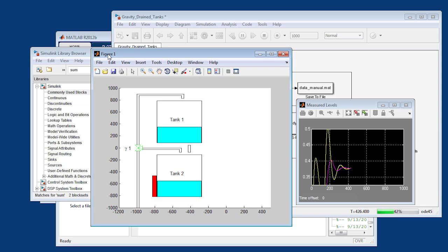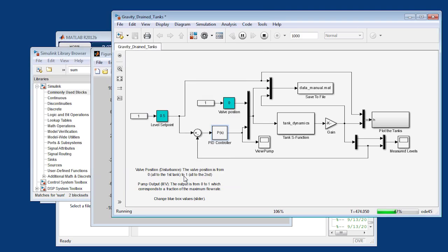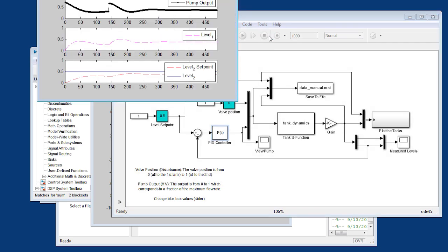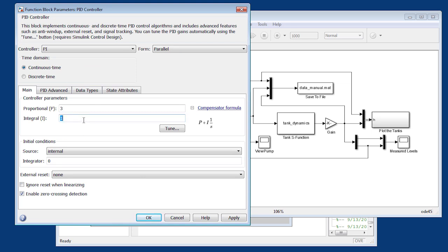Let's go ahead and just add in an integral term, just to see what happens. It looks like I can't change that while the simulation is going. So let me make this, instead of a P only controller, a PI controller, and let's go back to the original value, 0.77, and then I'm going to do 1 divided by 1.4 times 142. That's just a ballpark there.